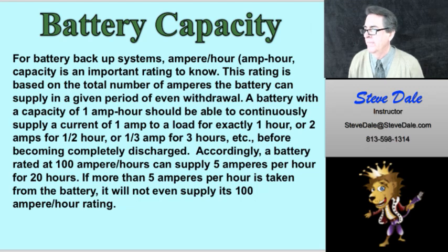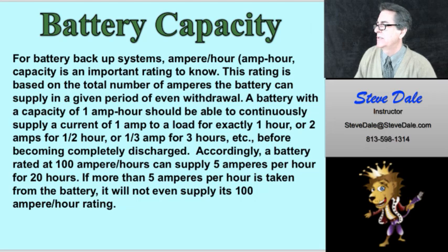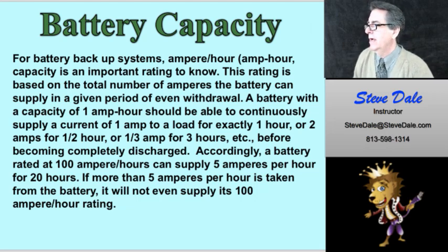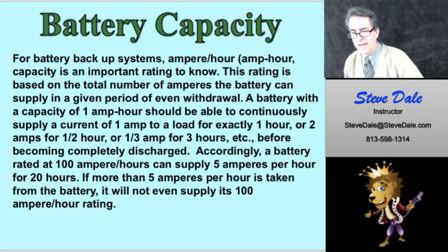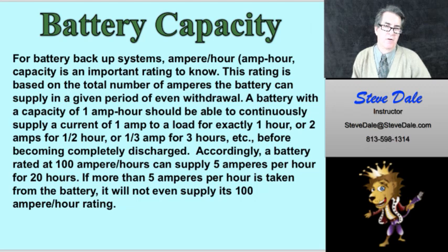It's battery capacity. Now, in our trade, with the alarm business, fire alarm business, you always have to have a backup battery source, even for telecommunications, all that stuff. You always need a backup battery in case the power goes out, right? You have to supply the system with current while the power's out until it comes back on. So a lot of times, especially with fire alarm systems and even burglar alarms, you have to calculate the amount of time the battery will last under load, okay?